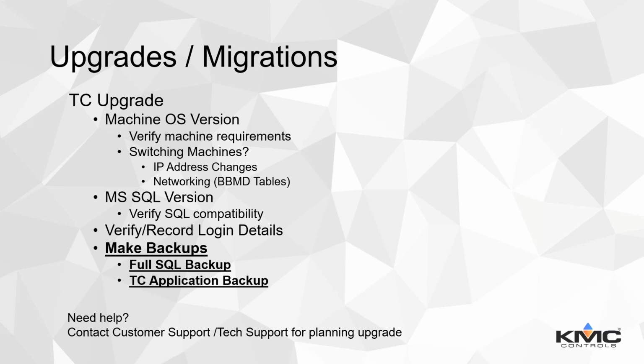You'll have a WinControl machine that's on an older piece of hardware, an old server or an old desktop, and you're deploying a new server for the customer, and it's running TotalControl. And the two can reside and talk to the devices together. However, we don't recommend that for long-term usage. It is okay to do during a changeover scenario for a period of time.